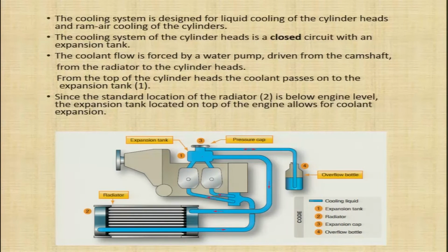The cooling system is designed for liquid cooling of the cylinder heads and ram air cooling of the cylinders. So, you can see this is a combination of air cooling and liquid cooling. The cooling system of the cylinder head is a closed circuit with an expansion tank. Now, you can see a schematic diagram here.